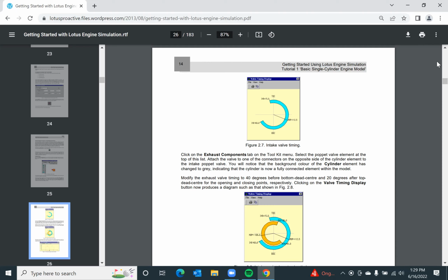What it means is you have a small region wherein the intake valve is open and the exhaust valve is also open. So do you see what's going to happen? Basically, the fresh charge would get contaminated, which would affect the efficiency. There are ways of dealing with that. Basically, you design the valves and you design the combustion chamber.